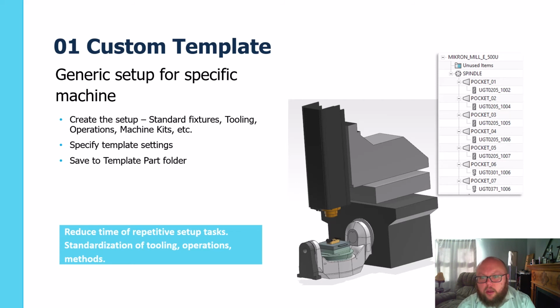Maybe we have a machine tool that we have resident tooling in the machine, and we want to load up the first 5 pockets, 10 pockets, 20 pockets with resident tooling that are always going to be in the machine, and then the remainder of the pockets in the tool magazine are then reserved for job-specific tooling that's going to come in and out of the machine with regards to what part we're manufacturing. That's one additional approach.